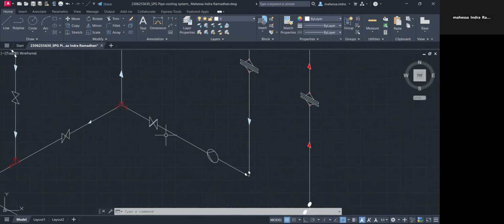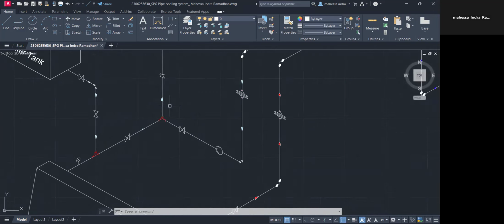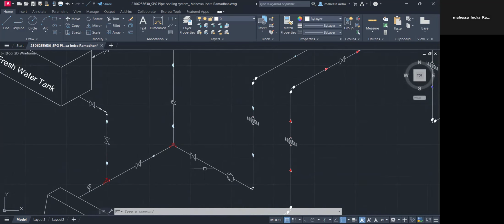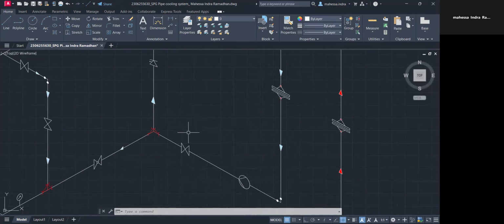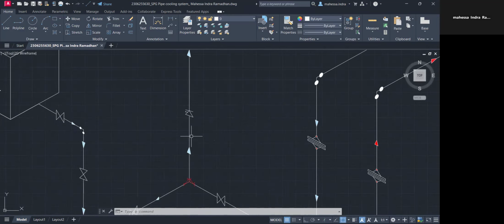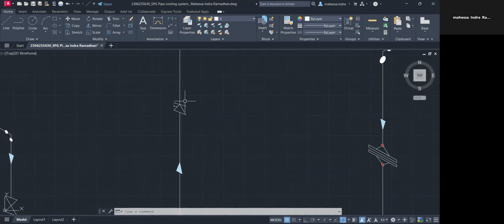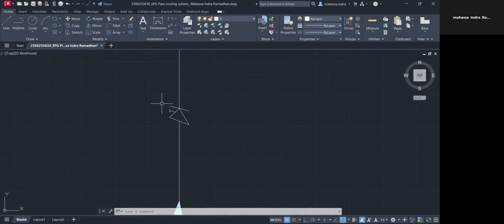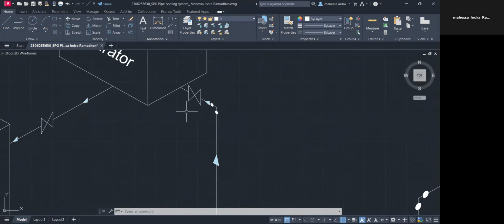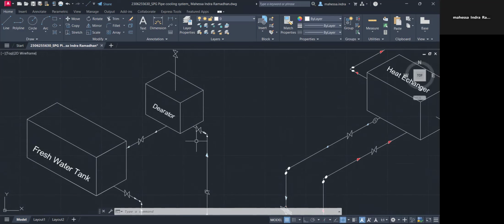It continues, helped by the pump, and the freshwater will meet the non-return valve. This is attached to prevent the fresh water from dropping back to the bottom, and then it continues to the top and we'll meet the deaerator again.